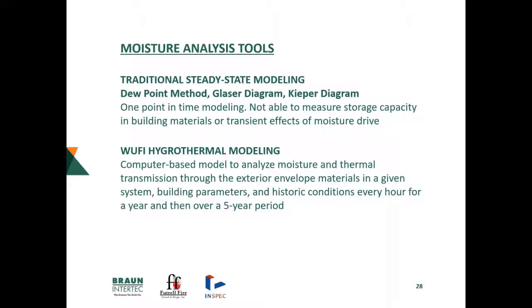So you can pick, of course, your coldest day of the year and run that dew point, and then find that maybe a couple weeks later it should be good, but it's still showing some moisture accumulation. Where when we use a WUFI model, we're able to see that through a period of hours, days, months, years, and see how that moisture moves in and out of that assembly.